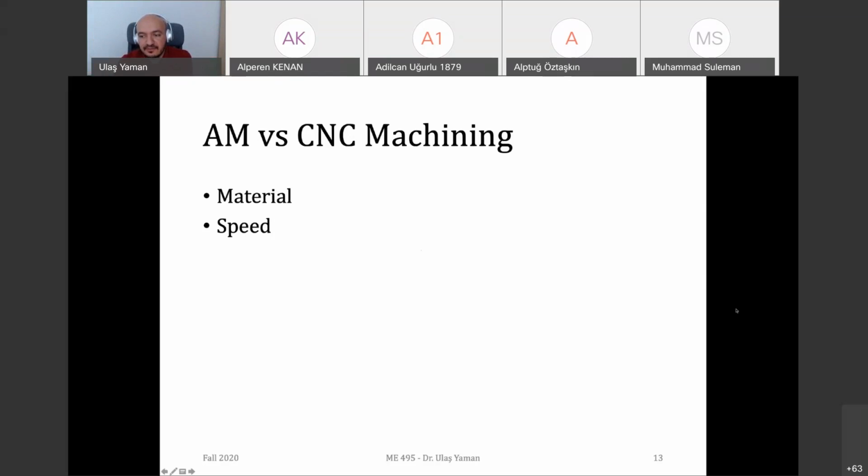Depends on the details. There are different answers. CNC machining is better in design and production, I think, in case of speed. But what about CAM part? In the complex manufacturing parts, depending on the complexity of your part, you need to spend some time for sub processes. You should tell that there should be, let's say, tool drilling operation, tapping operation, and shouldering operation, facing operation. You need to do a setup. You need to have some fixtures. You may need to design some special fixtures.